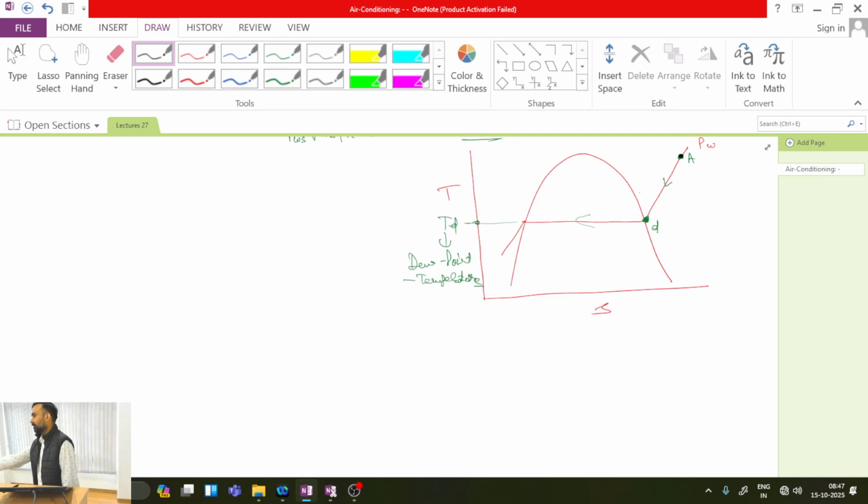If we have some water glass in this room and air is not saturated, you will find next morning that the water in the glass has evaporated. If the room is perfectly insulated, it means that for water to evaporate it requires latent heat of vaporization. From where has that latent heat of vaporization come? From the surrounding air. So air will be losing energy in order to evaporate the water. Is this point clear? So if I use a pool of water and allow air to flow over it, that air will be evaporating some amount of water.